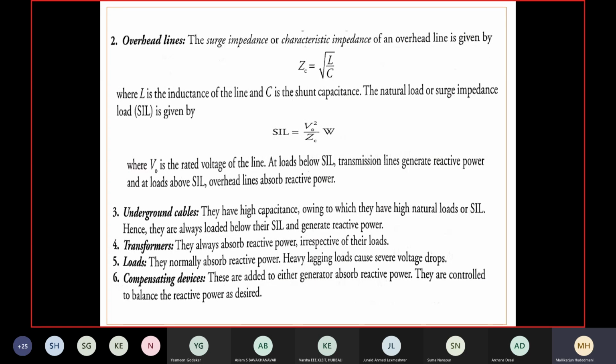Because of that higher absorption, systems suffer from inductiveness. When the system becomes highly inductive in approach, the overall power factor of the system falls. Operation of a system having a sluggish power factor becomes very challenging and adverse. We all very clearly know poor power factor results in higher current requirement, then higher losses, pulsations, and all other associated adverse effects of poor power factors are noticed.